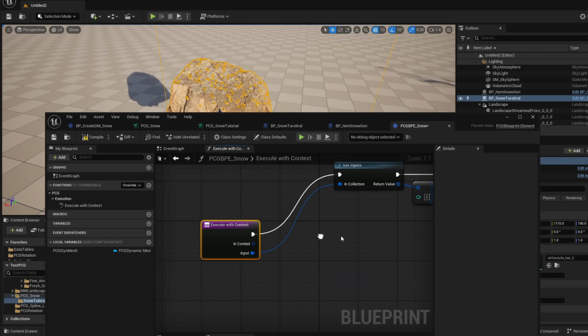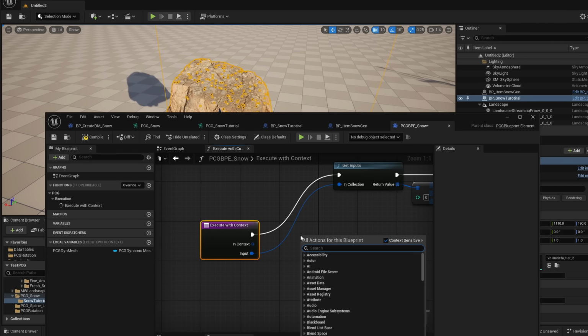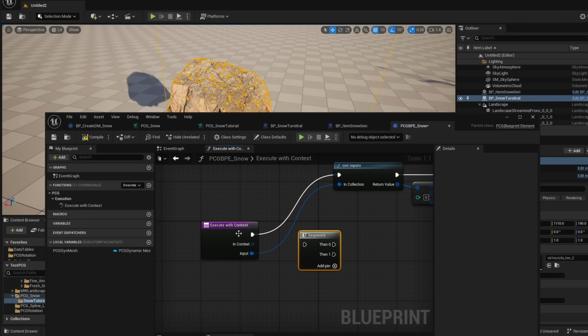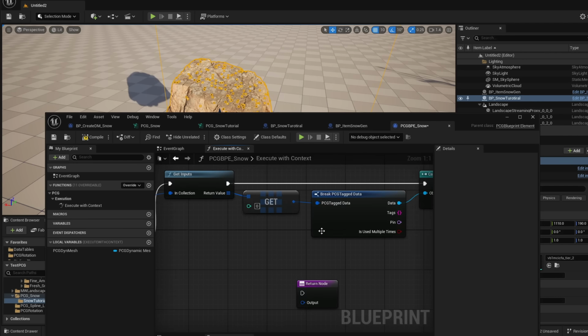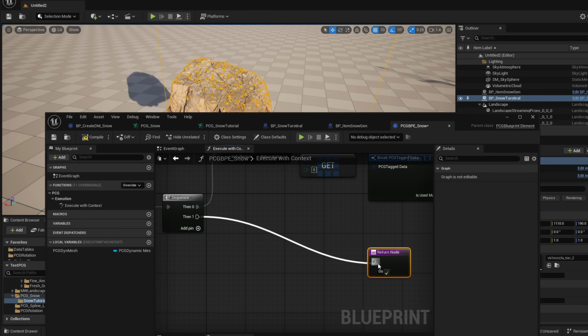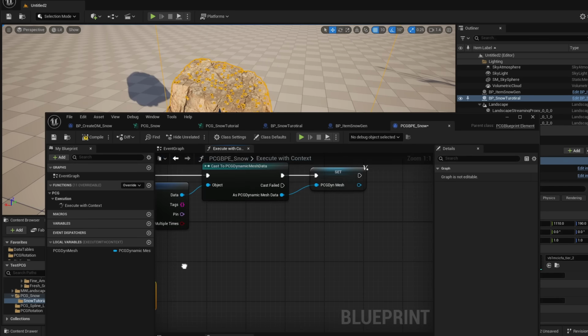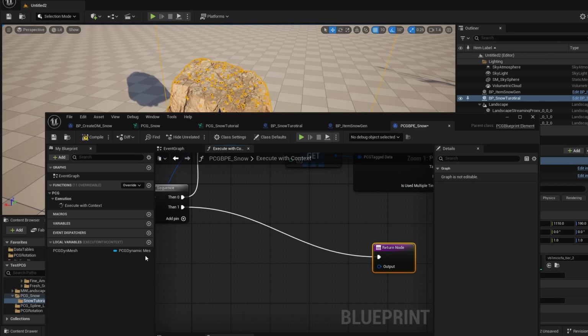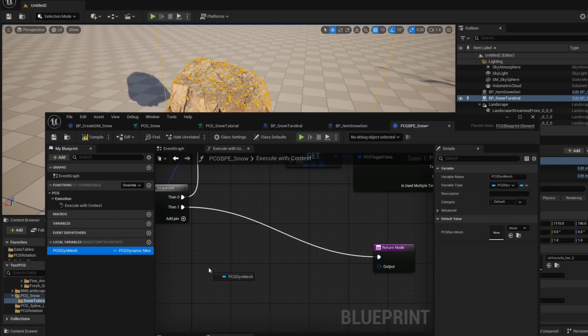And after we save this, let's create a sequence node. After we save this value, so first this sequence is running first this, then 0, and after it's done, let's then output the value that we want. So the value that we want to output will be this dynamic mesh that we got into the input.